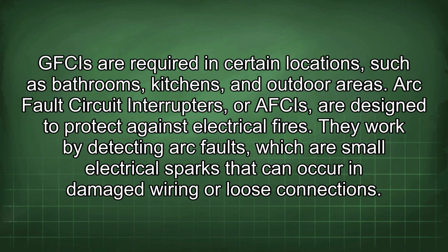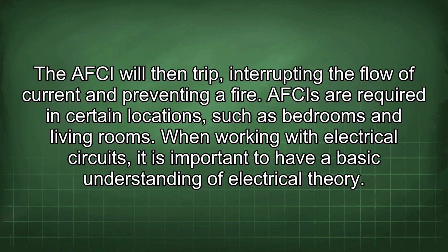Arc fault circuit interrupters, or AFCIs, are designed to protect against electrical fires. They work by detecting arc faults, which are small electrical sparks that can occur in damaged wiring or loose connections. The AFCI will then trip, interrupting the flow of current and preventing a fire. AFCIs are required in certain locations, such as bedrooms and living rooms.